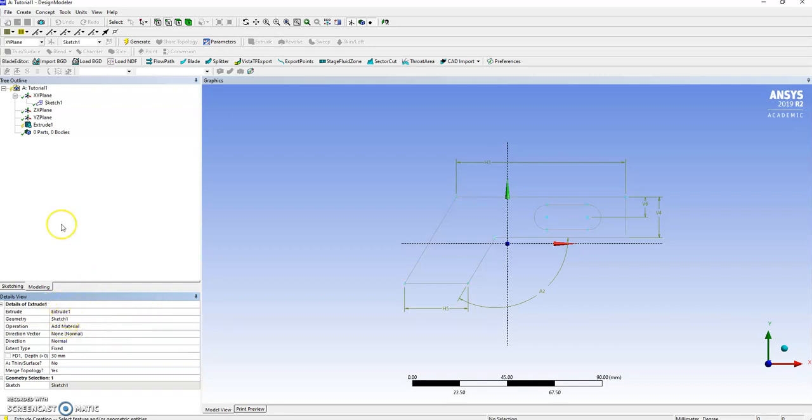Geometry, okay, apply. So usually you select something and apply it based on sketch number 1. And what is it doing with it? It's adding material. We'll talk about the difference between add frozen material at another stage, but at the moment, they're equivalent. Vector, normal, direction, whatever, the depths, let's make it relatively thin at 10 millimeter or 15 millimeter.